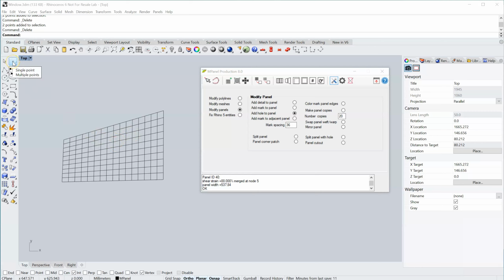We'll add some Rhino points which will define the shape of the cutout or window. For this example, I'll only add 4 points defining the corners. We could add more points if the window shape included one or more curved edges. If an existing cover is being digitized using either a laser or a ProLiner device, these extra points defining the window shape would be added as part of the data capture.